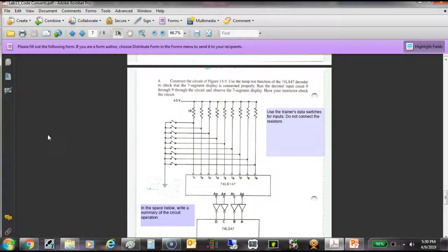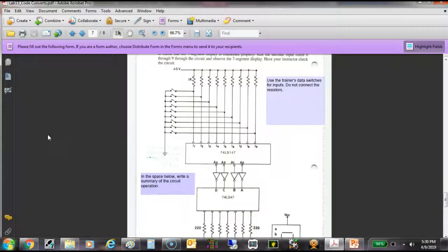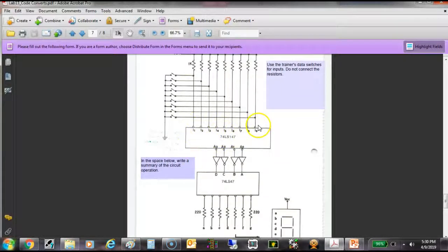Here we go. This is the last circuit we're going to check up, and I think I've already told y'all this is an encoder. It's a 10 to 4 encoder. So what it's going to do is take a decimal number over here between 0, which is not shown. So if none of these are true, then of course that means it's a 0. It's a low active input, so this would come out of either a 7442, which has low active outputs, which is a 4 to 10, so this would come right out of that thing.